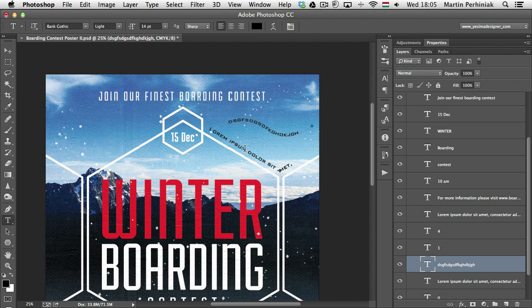But you can also use shapes, like I'm going to use the polygon tool and set to the path mode. I'm just going to draw a hexagon, following again the design. And then once I switch to the type tool, it will again show me a different cursor with which if I click on this shape, I can again paste in text.